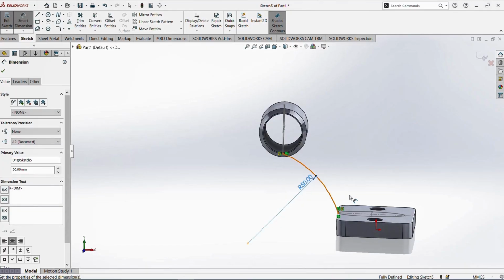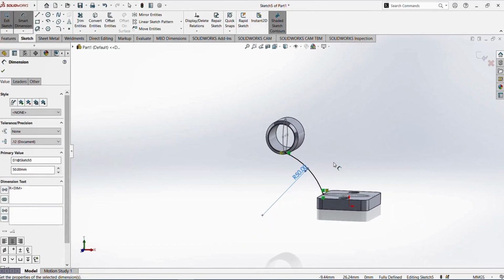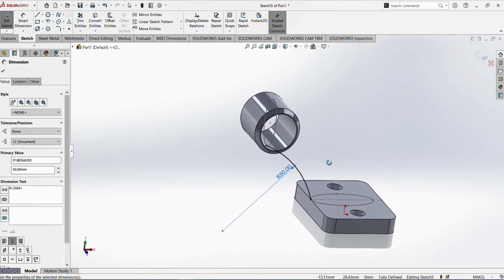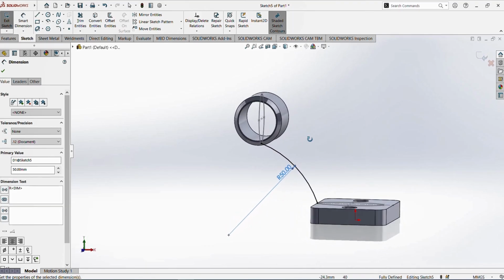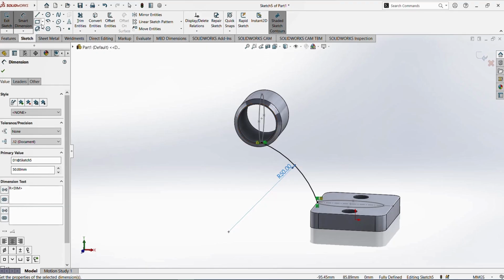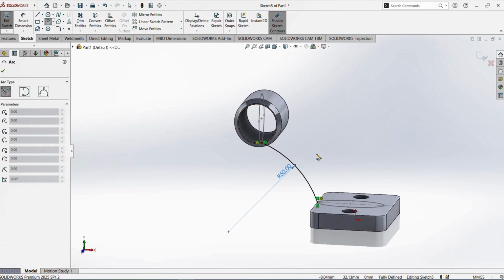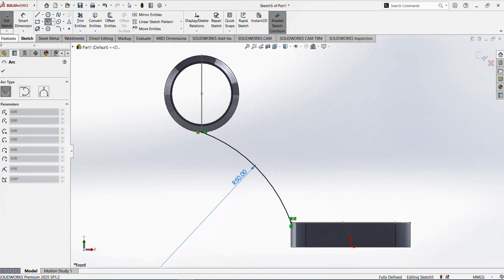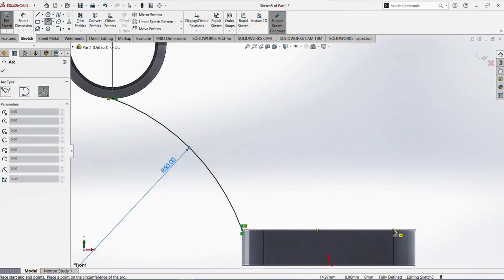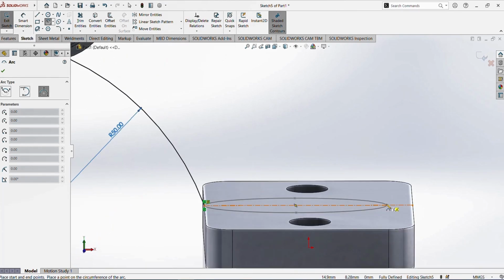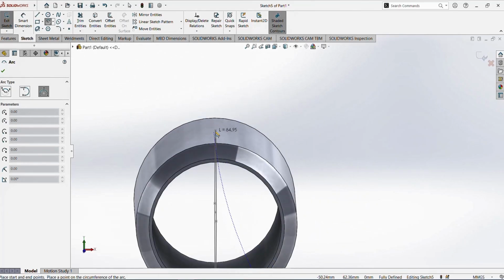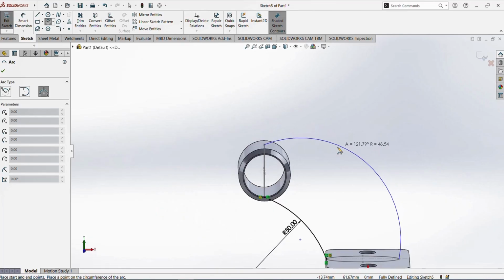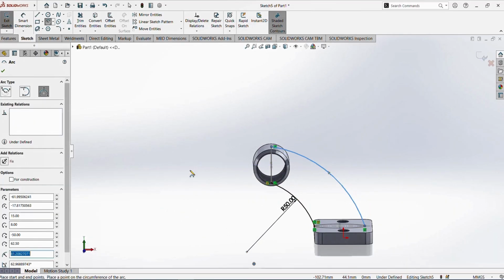In this sketch, this is a continuous sketch. You can also draw the second guide curve in a single sketch. Again I select the 3-point arc. First point here, do not select this point, because the ellipse is up to this point. So I select this point as the first point of the arc, second point is this point, and third point is the direction.